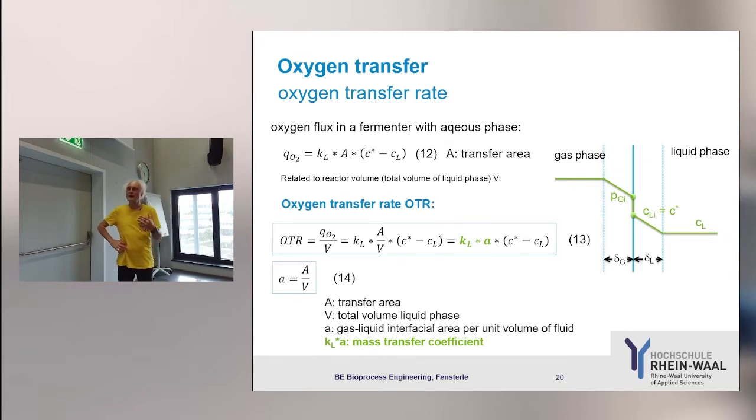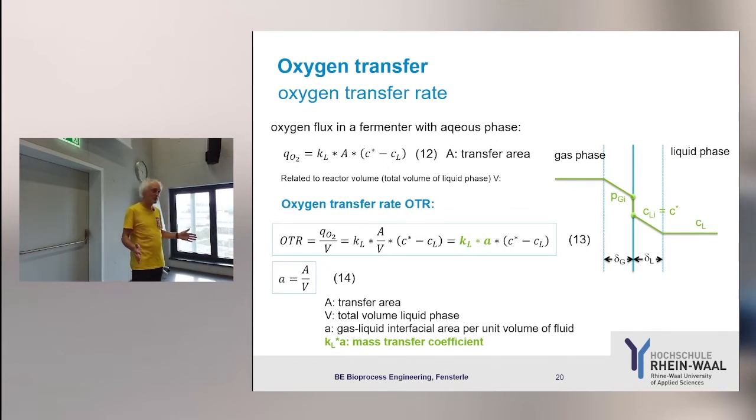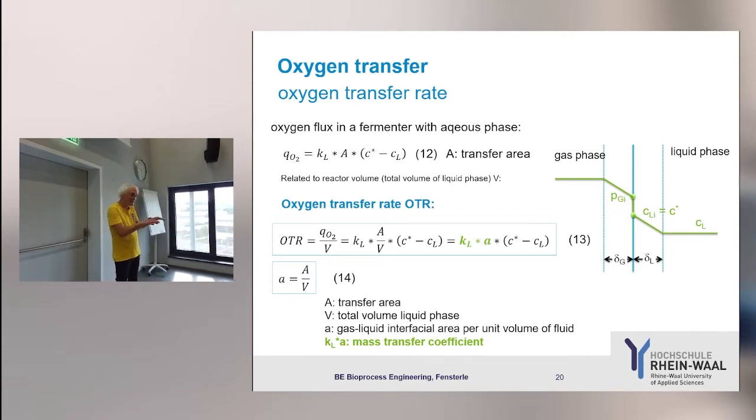In all these equations, we have this thickness of the film coming from the two-film theory, which goes, of course, into that, because we have a tabulated diffusion coefficient. This is something which can be measured. So you have a pure diffusion process and measure this diffusion coefficient, and then we have this thickness of this layer, and then we have the area.